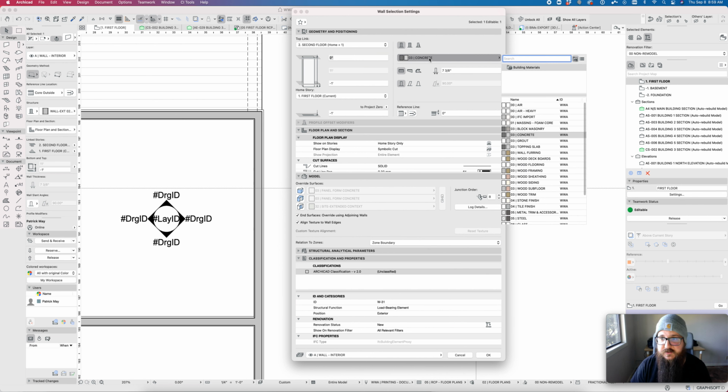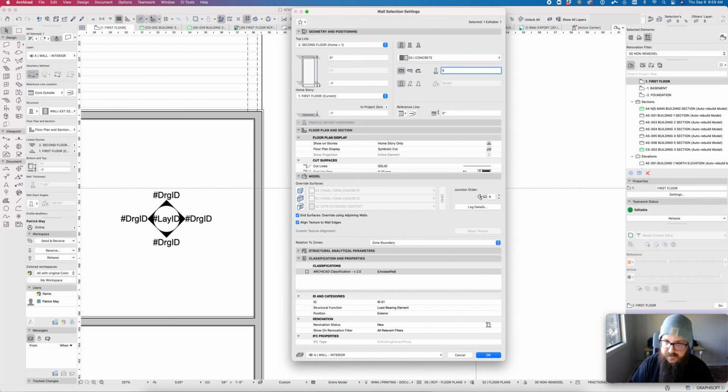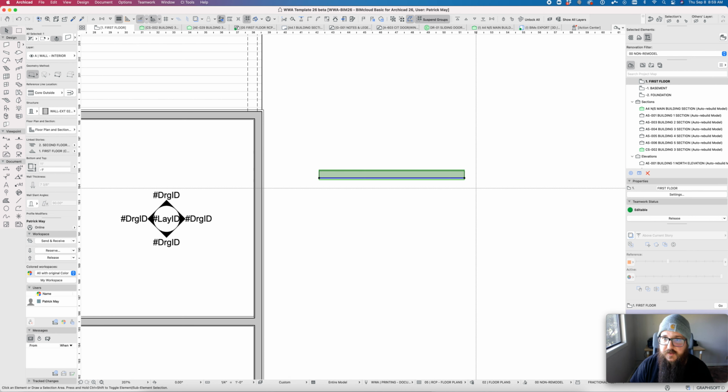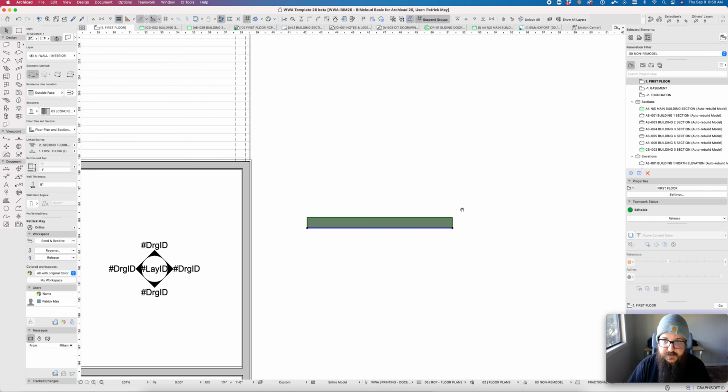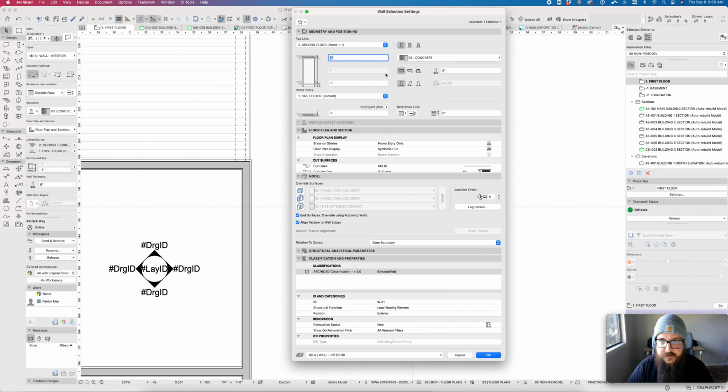want to set this to concrete and just say that this is an 8-inch concrete wall. The problem with that, and it does look graphically right, but if we have a dozen different concrete walls in our project, or 100 or 1,000 different concrete walls in our project, and we find out that those concrete walls need to go from 8-inch to 10-inch, you're tasked with picking through every single instance of those concrete walls and changing them all in their thicknesses.